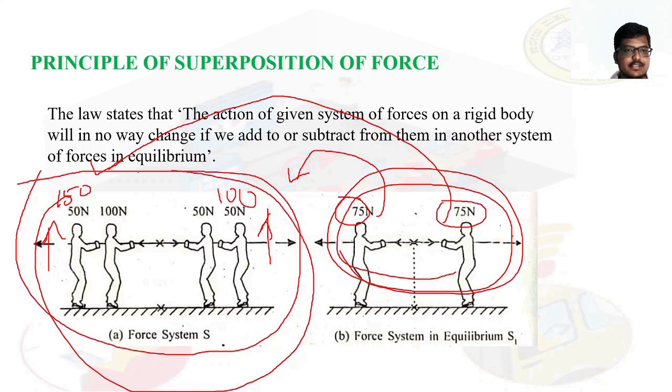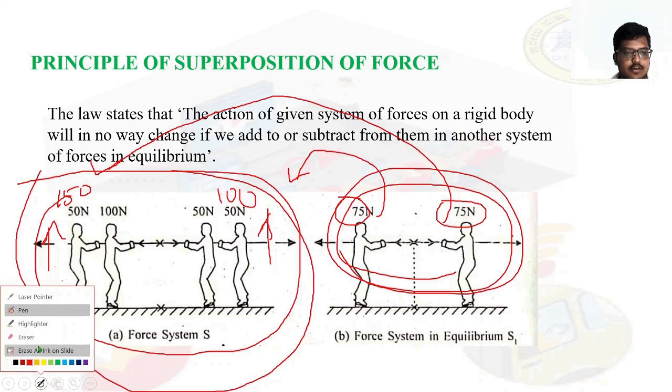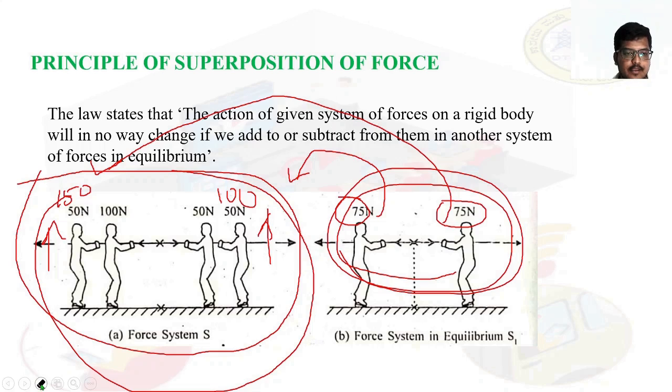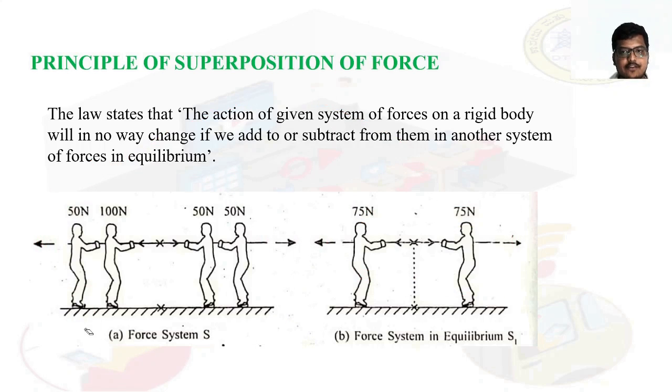Yes, so this is the principle of superposition of forces: the action of a given system of forces on a rigid body will in no way change if we add to or subtract from them another system of forces in equilibrium. Okay, this is the principle of superposition of forces.